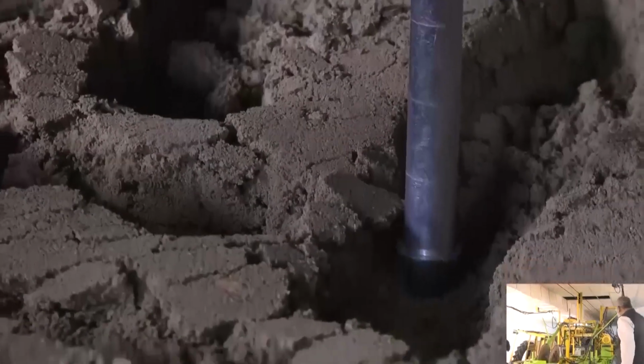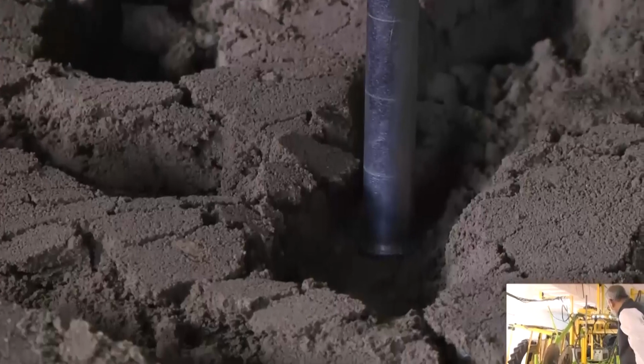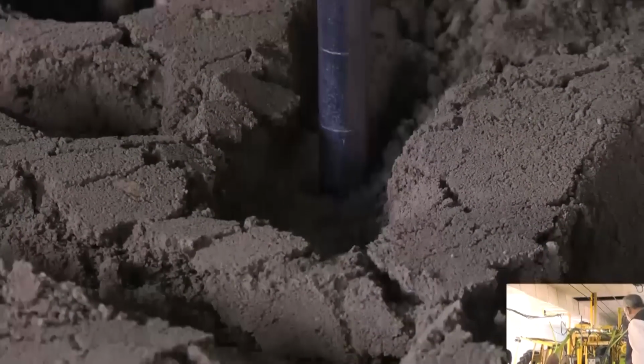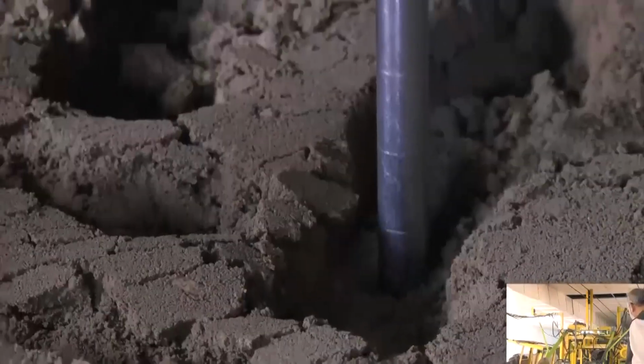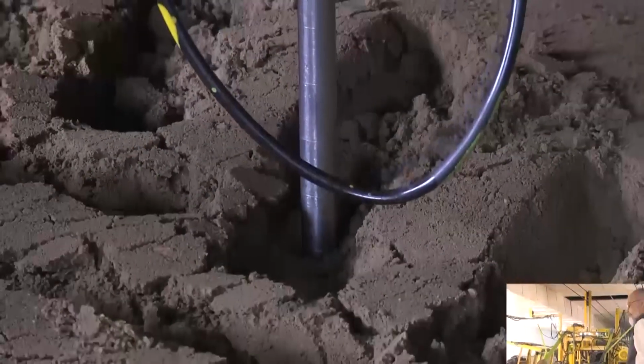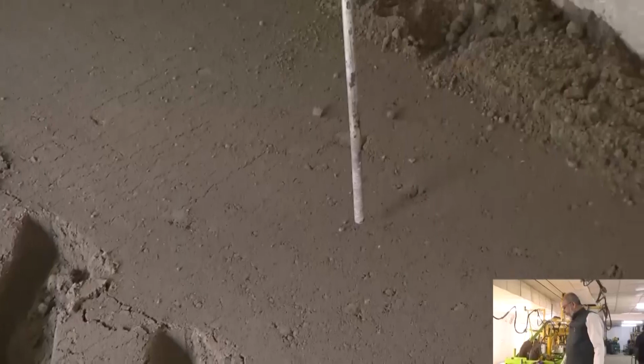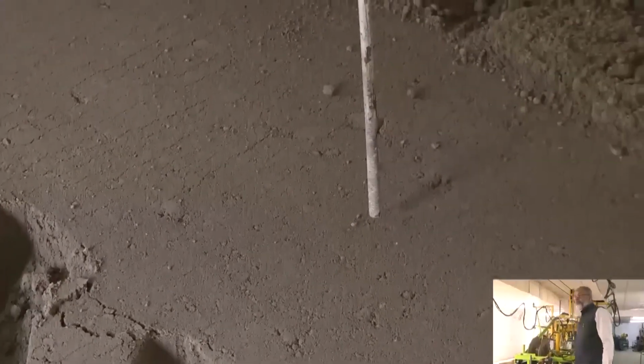Now he has made it 0. So this shows the 0 label. Now he has pushed the cone penetrometer into the soil. So that will give you the strength of the soil after operation of the tire. Try to measure the sinkage level after the operation of the tire.